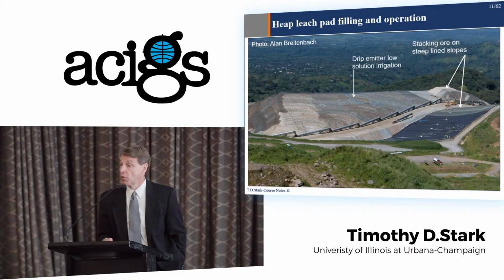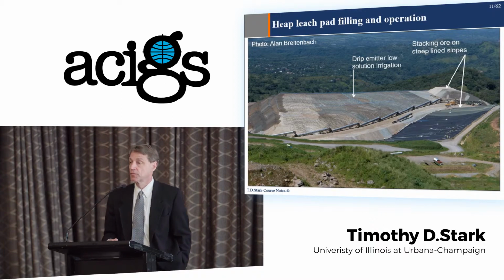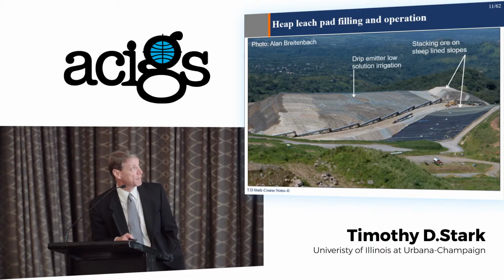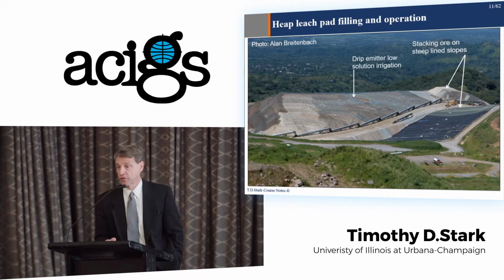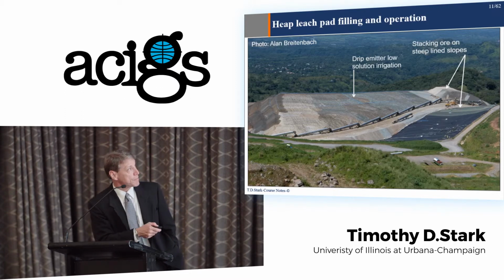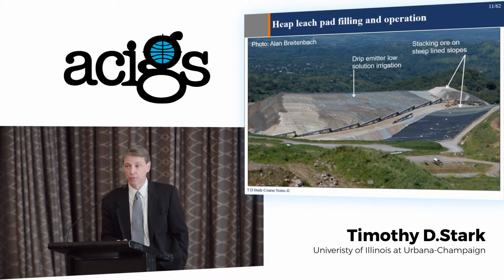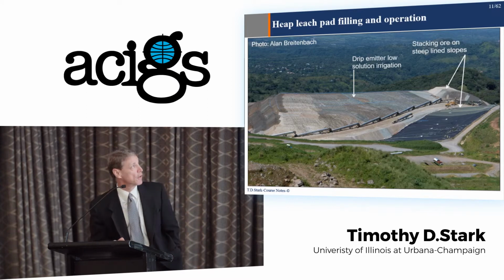exceed, say, 3 to 1, and of course when we get steeper slopes we have concerns about slope stability, especially with a lined slope, because we have a geomembrane involved which could have a low interface strength associated with it, or some other geosynthetic. So there's the lined slopes, the conveyor bringing the ore to the back, irrigation and solution being added on this segment, and so there's a good picture of the full operation of the heap leach.